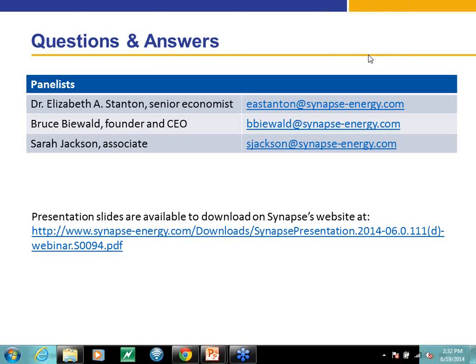Please walk through what would happen to the emission rate calculation with the addition of new nuclear generation in a future year. So just generally, new nuclear is something that would appear in the denominator of the 111D emissions rate equation, as would a variety of other things. If you have new wind or what have you, that fits in the denominator where the megawatt hours are added up. So if you have new nuclear, that would make the denominator of your equation bigger, which would make your ratio, your 111D emissions rate, smaller, which is what you're going for.